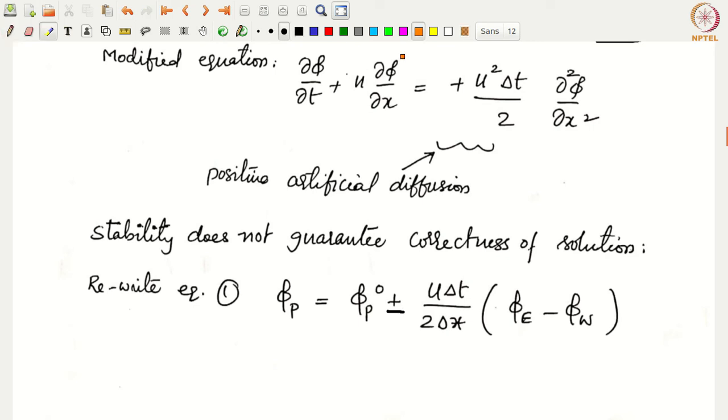Fine. All right, so what we have here is coefficients with opposite signs. This would always produce oscillations, as a result of the negative coefficients that we have. And it doesn't matter whatever delta t we take, this will always produce oscillations. So that's the reason why the solution will not be physically correct.